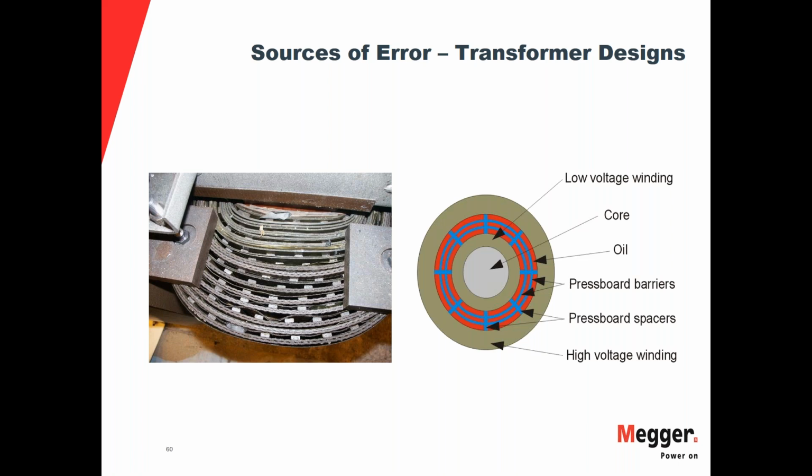So just because you're using the step up method doesn't mean it's always the right choice. Step down may be the right choice. Again, we're going back to design, we're going back to characteristics of the unit. Especially on pad mount transformers, the spacing between high voltage and low voltage is going to be different. It's usually much closer. And then you've got different permeabilities and you have different coupling.